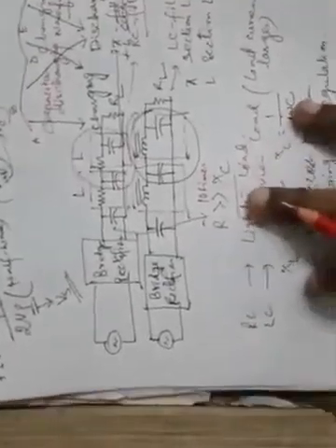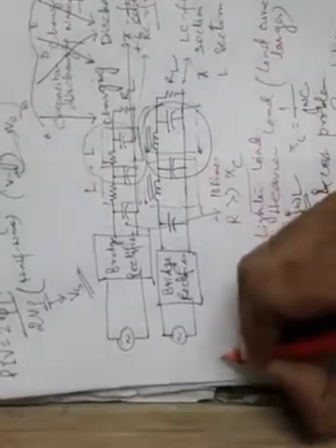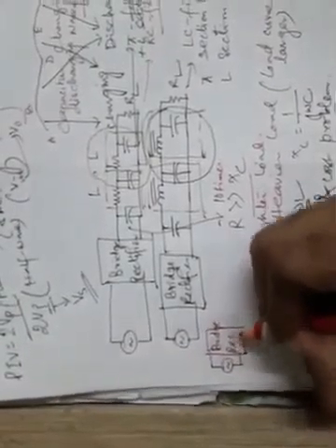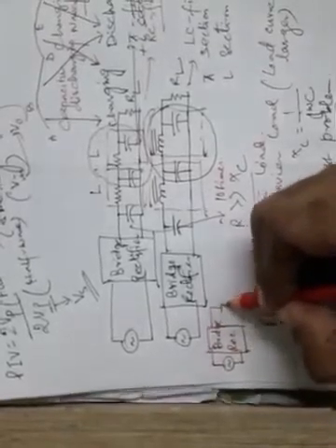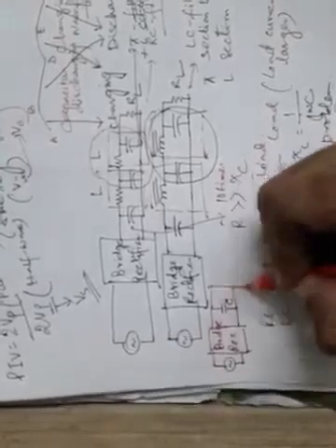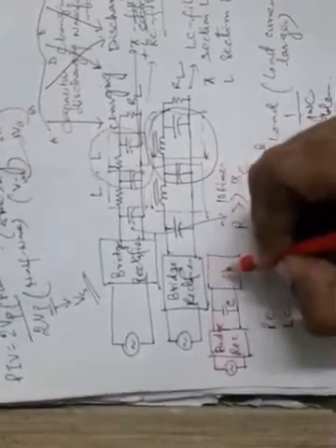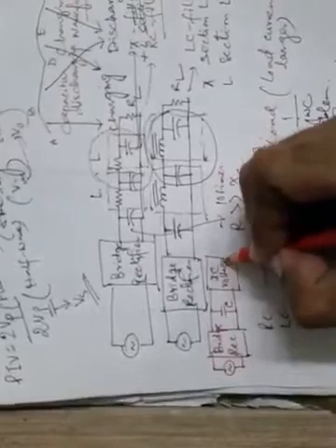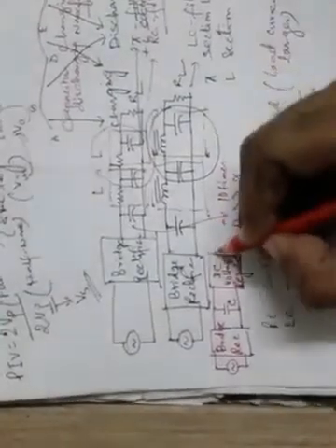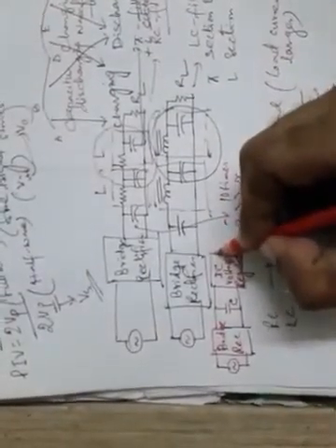So now let us see the IC voltage regulator as well as the filtering scheme. A small diagram like the previous one: AC source, bridge rectifier, and at the output of the bridge rectifier a shunt capacitor filter is connected, and that is directly connected to a filter cum regulator which is called the IC voltage regulator, which is doing filtering plus regulation, and then the load resistance is connected at its output.